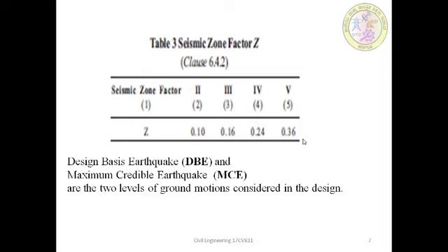Hence, if the earthquake unfortunately strikes, care is necessary to reduce the damage. At the same time, there is no rationale in designing the structure to be safe against this earthquake, which means a highly uneconomical design. Therefore, the design under MCE is called a level 2 design, and it focuses on imparting ductility to the structure.